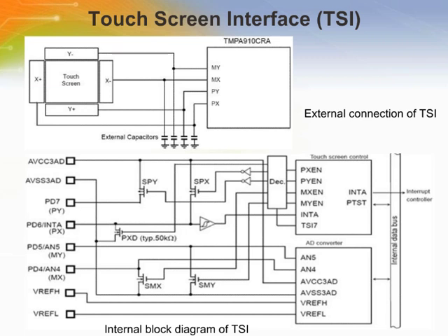The touch detection procedure includes the procedure starting from when the pen is touched onto the touch screen until the pen touch is detected. Touching the screen generates the interrupt INTA and terminates the procedure. After measuring an XY position and an XY position measuring procedure is terminated, return to this procedure to wait for the next touch.